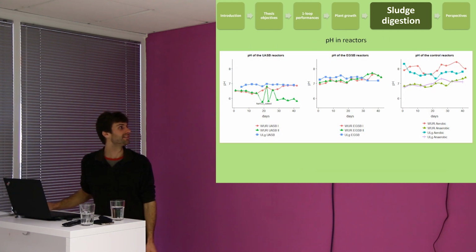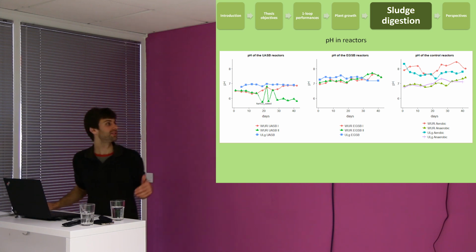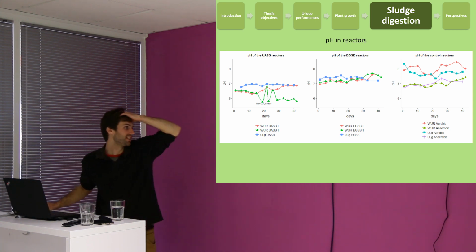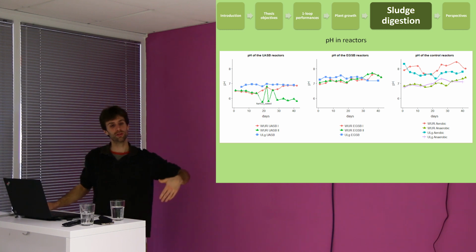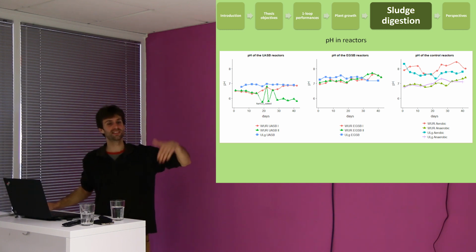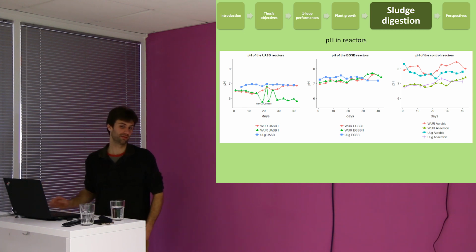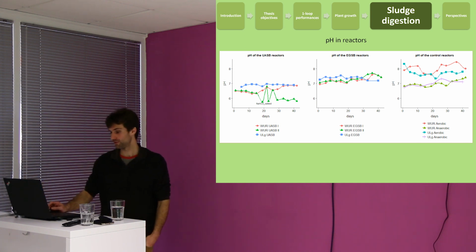But you can prevent it. If you see that the pH drops too much, we put sodium carbonate to raise it. But you should manage the pH before it starts to drop. When it starts to drop, it's already too late, because we tried and Simon tried, and he couldn't get the pH up again. It was like the process crashed. So this is something important for the future.